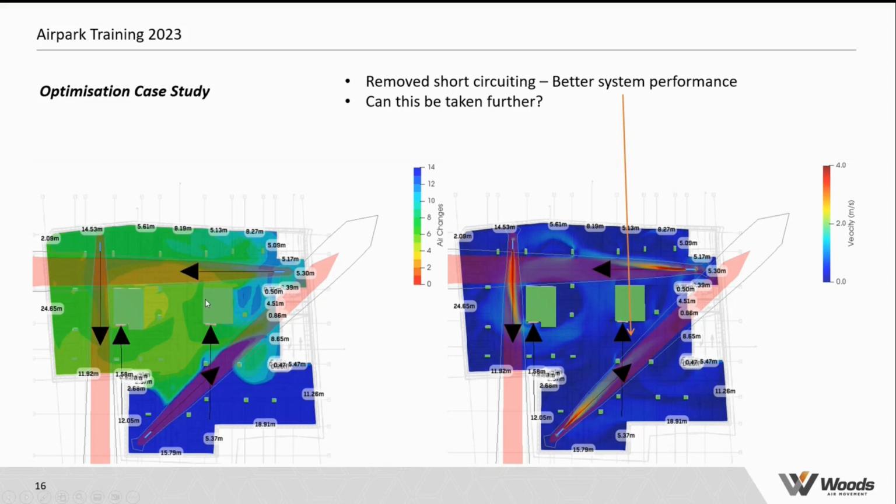By doing this, we've recreated this wall. Well, it's not really a wall, but it's an air wall in the car park, separating the two sides, preventing the supply air from getting over here, and then preventing the air which has been directed around the car park to ventilate it from escaping and recirculating, allowing it to be collected by the extracts here. So once again, we now have a functional, well-performing system, largely free from problematic airflow structures.